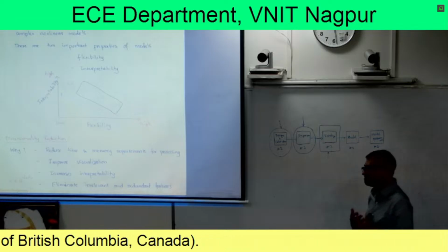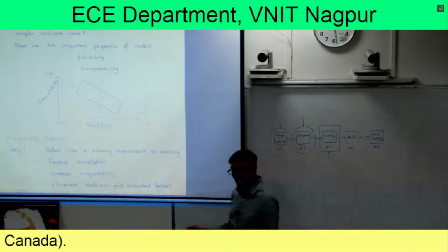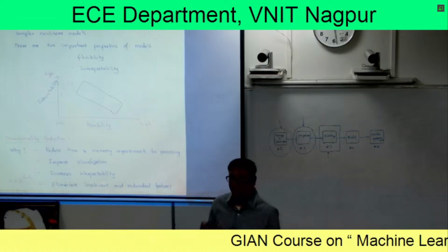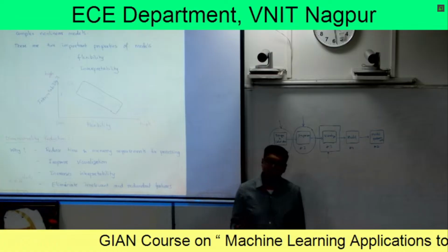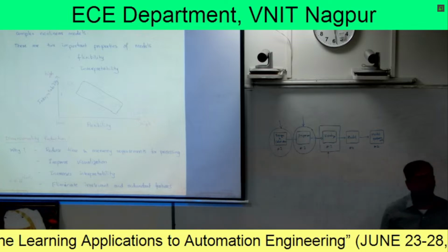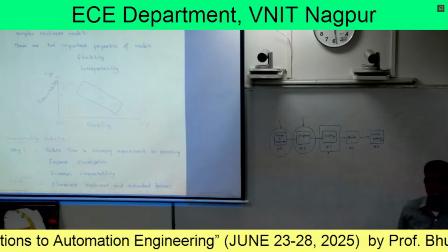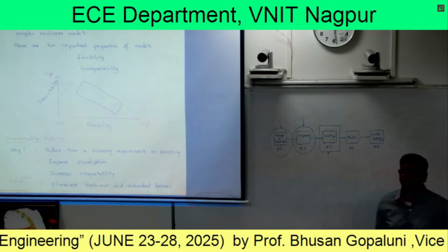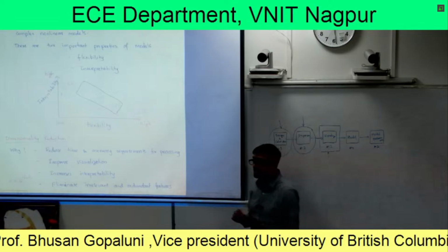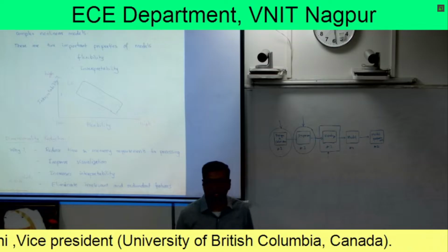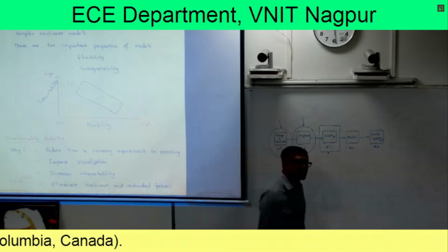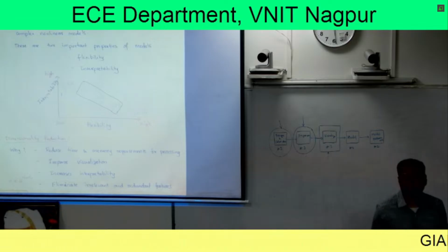If you have a simple mechanical system, let's say a pendulum, there are very good physics-based models you can use on a pendulum, right? On the other hand, if you have a complex industrial process, say a distillation column or something like that, even there you can build first principles models. The only question is, do they truly reflect the behavior of your system because of various disturbances and noises that may or may not be accounted for in your first principles model?